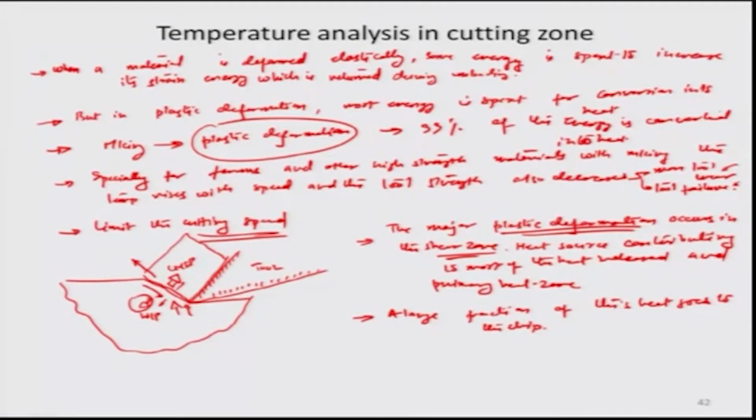There is another reason why heat should occur, and that is because the chip is moving at a certain velocity with respect to this tool face right about here, and so the sliding motion of the chip also generates heat energy, and this energy is primarily generated in the tool face because of the frictional force that the chip would have against which it has to move at a certain chip velocity Vc.